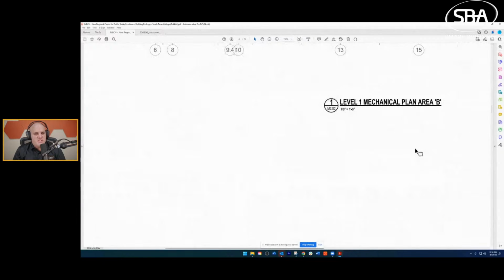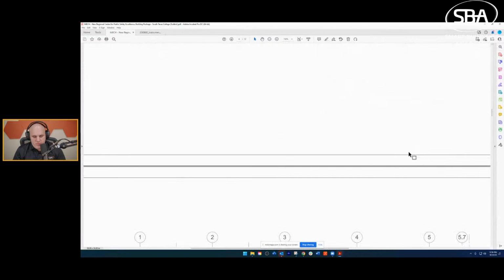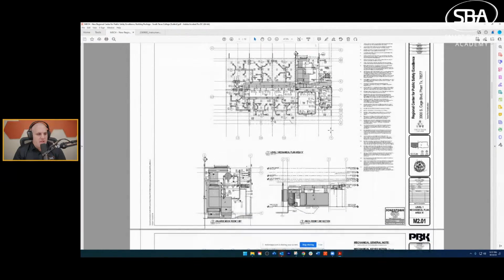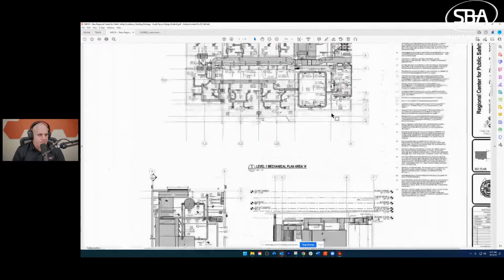Some of the common misses that I see are people missing who includes mechanical materials. Like sometimes the valves and actuators are included by others, installed by controls contractor, or included by controls contractor, installed by others. That's something you need to catch. Integrations are a big thing to catch, as well as being able to use controllers for other systems that may be nearby. Like right here, right?